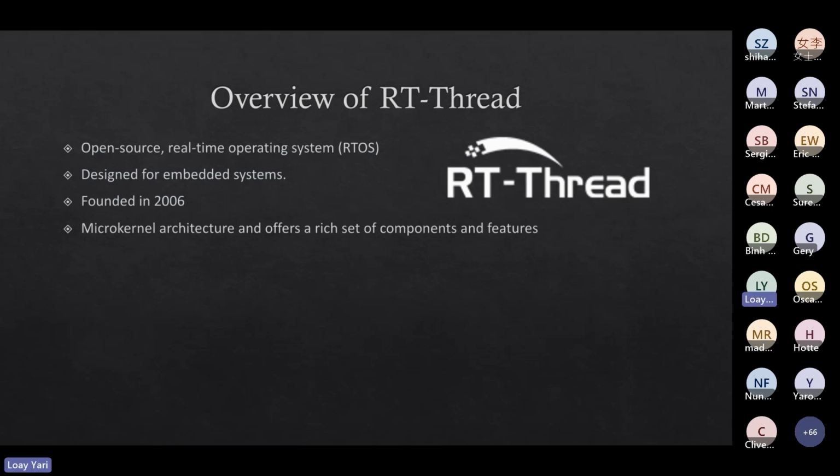Also, another feature is the POSIX standard compliance. This feature enhances portability and makes it easier for developers familiar with Linux to use RT-Thread. The device driver framework is also offered by RT-Thread, allowing developers to create and manage device drivers efficiently. File system support: RT-Thread supports a range of file systems, enabling it to handle data storage and retrieval tasks effectively.